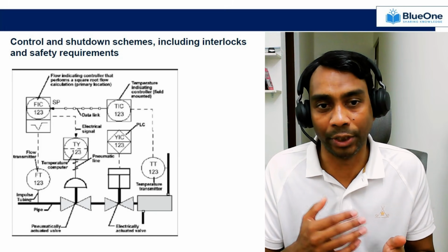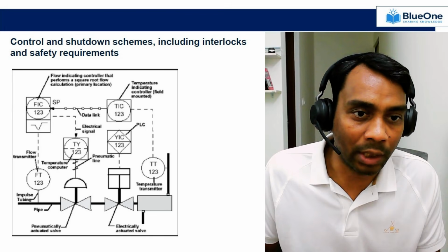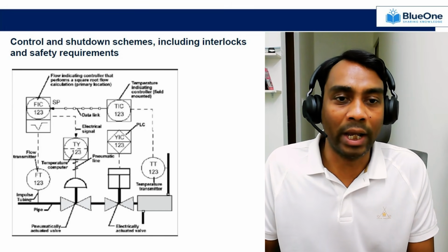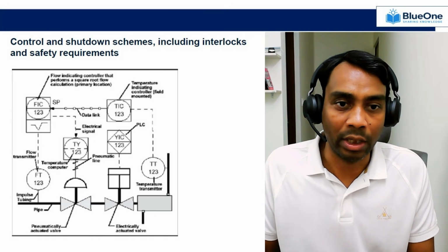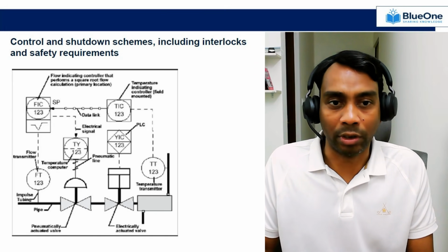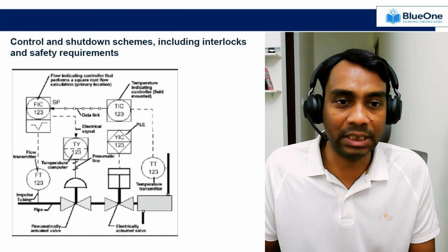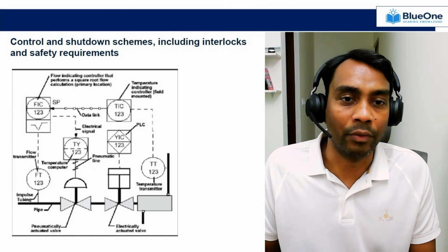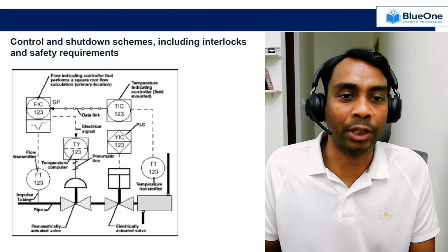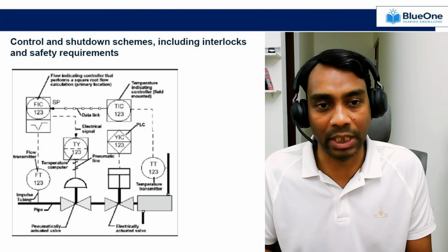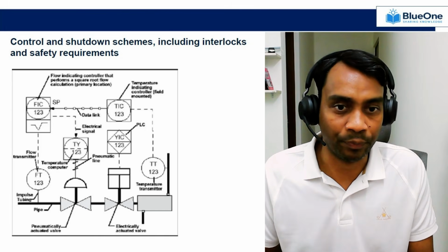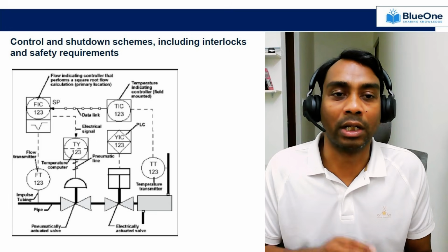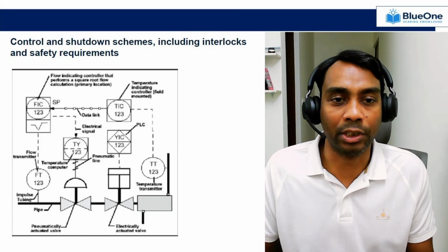so the valve will be operated. In addition to this process control loop, you can see also YIC 123, which is controlled or interlocked from the PLC. So there is a shutdown valve or isolation valve, which is directly receiving an interlock from the PLC. Okay, so you have in this one particular diagram, you can see the process control loop, and you can see the interlock loop.